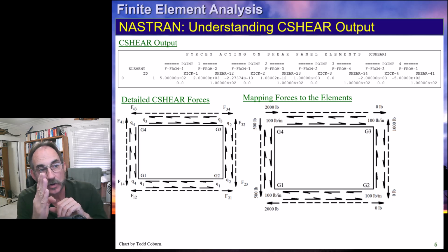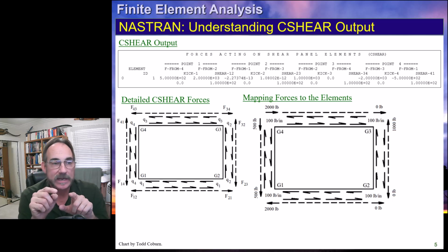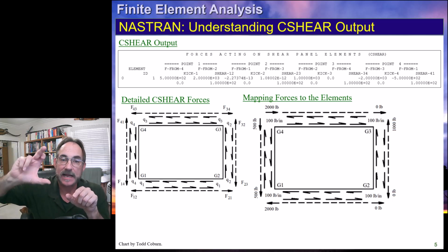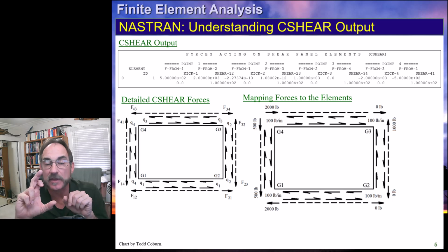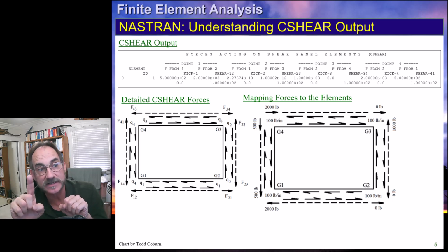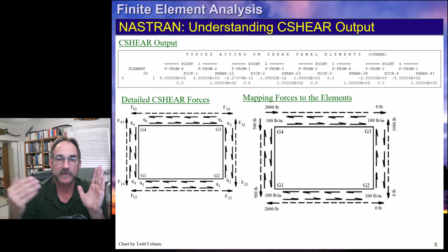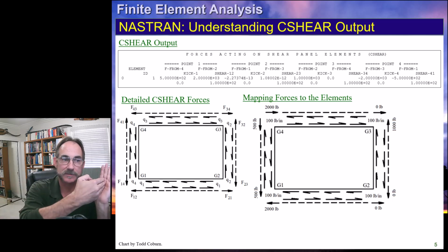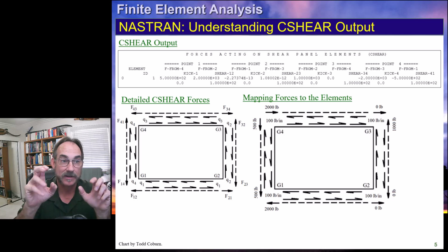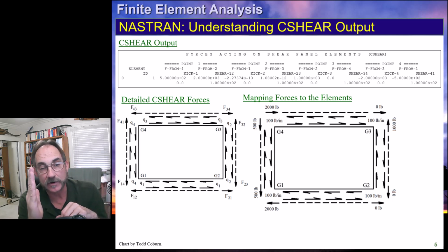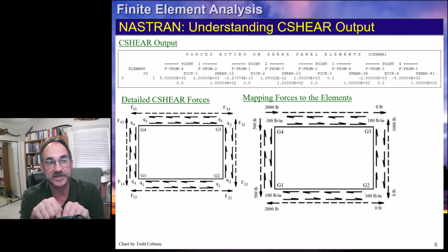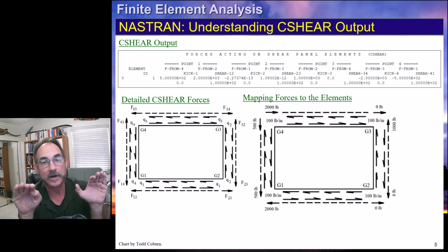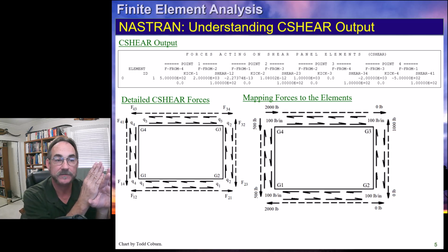Now, if we look at the vertical rod on the right, we had a 0 on the bottom, and yet we have a shear flow of 100 times the distance, which is actually 10. So 1,000 pounds accrues by the time we get to the top. So the bottom rod is going from 0 at the right to 2,000 pounds. The right vertical stiffener is going from 1,000 pounds to 0. The upper cap is going from 0 to 2,000 pounds of compression.